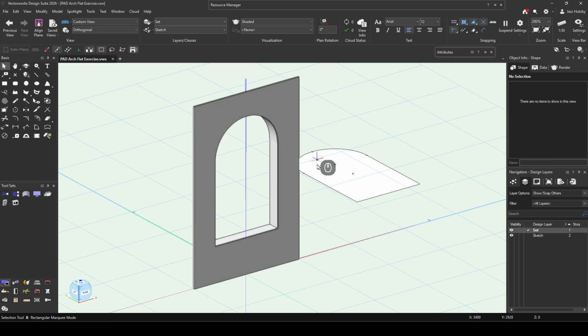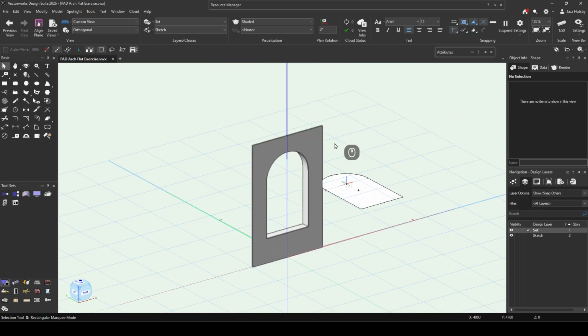And just to show you the power of that, or the benefit even, is that this internal window cutout that we just kept, just in case it's going to be handy, is still visible in our drawing. When we've done sketching and want to start to present and move things around, in the visibility, so in the navigation, in both class and design layers, we have little visibility columns.